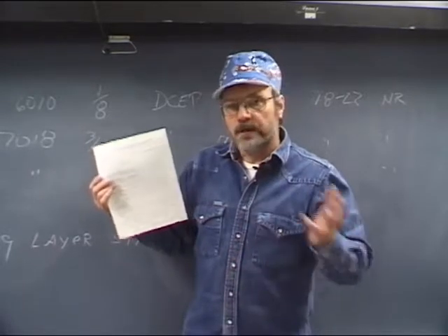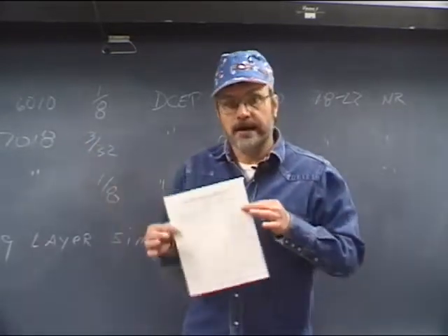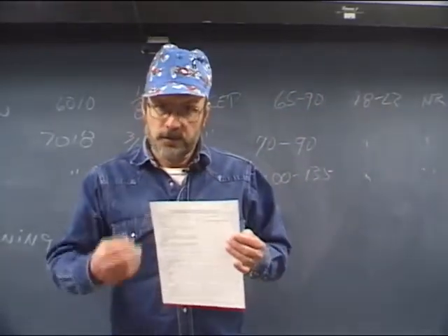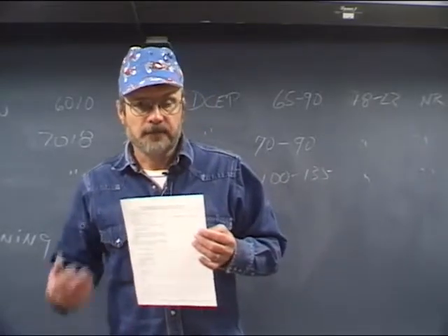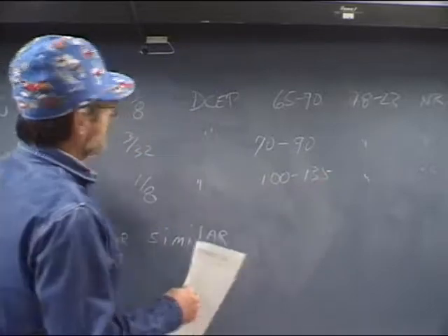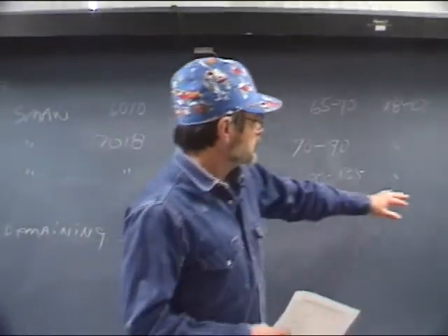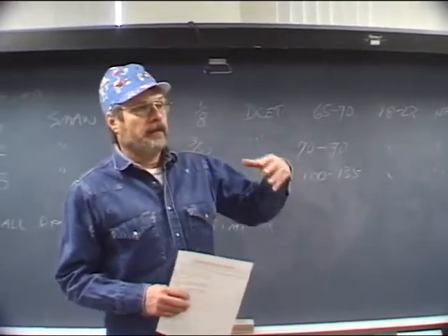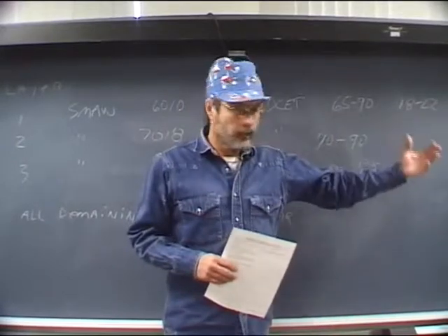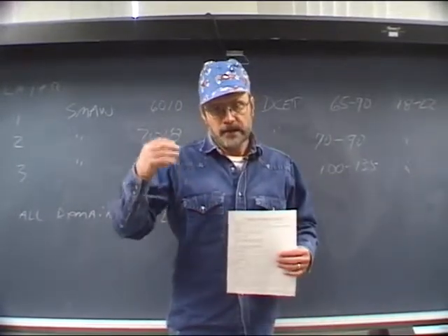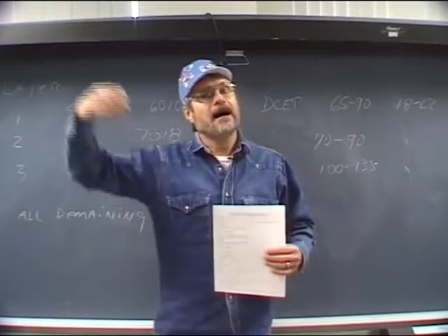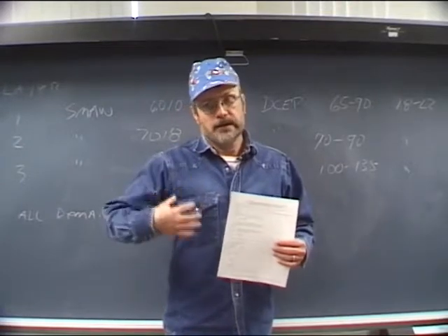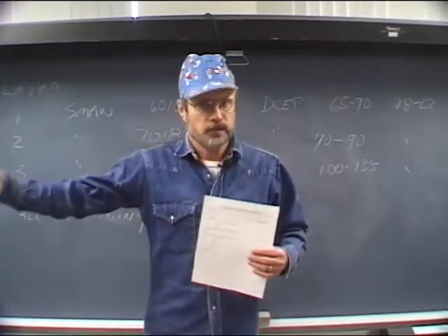And then, of course, if you have to make any changes down the road, then you have to do a revised procedure. If any of the variables, these are all called essential variables that we've been discussing, get out of the ranges that we've established, if you suddenly decide you're going to weld them at 150 amps instead of staying at 135 or below, now you have to do a new procedure. You have to do it all over again and establish that the mechanical properties are still going to work at that higher amperage. You've gone beyond the essential variables that we've already qualified. So now you got to do it all over again to reflect the new conditions.